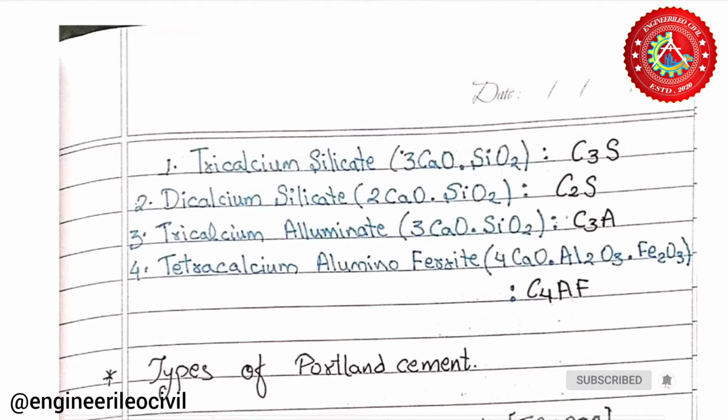C3S and C2S contribute most of the eventual strength. However, initial setting is due to C3S. C3S quickly hydrates and contributes initial strength. The contribution of C2S begins after 7 days of mixing and extends up to 1 year. The strength of the first 24 hours is imparted by C3S.